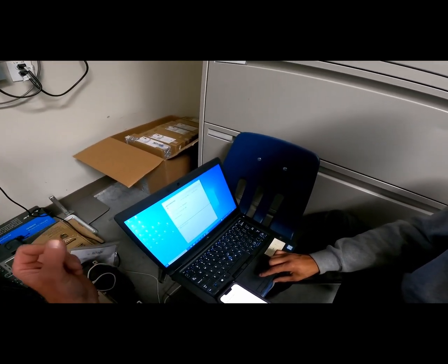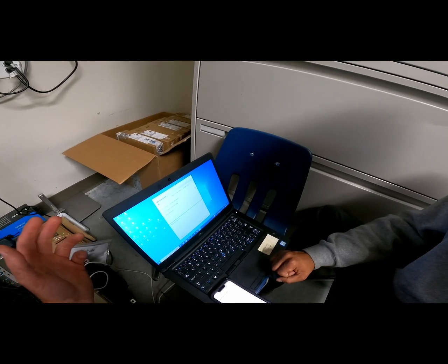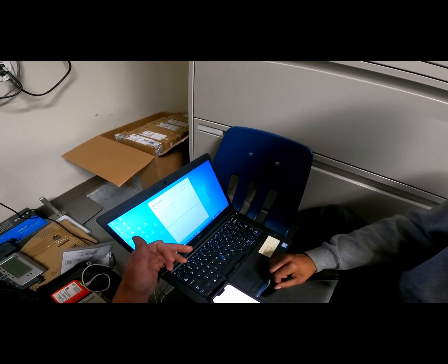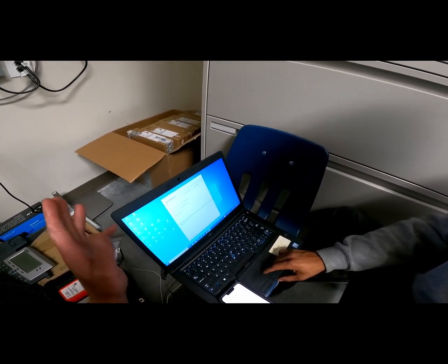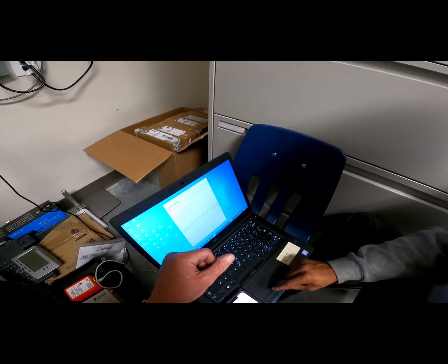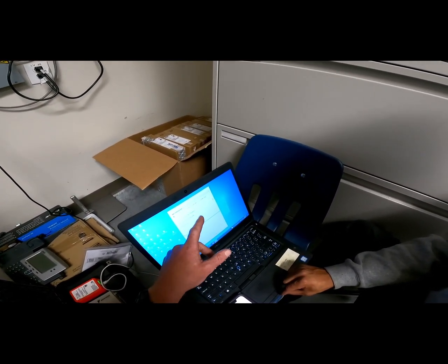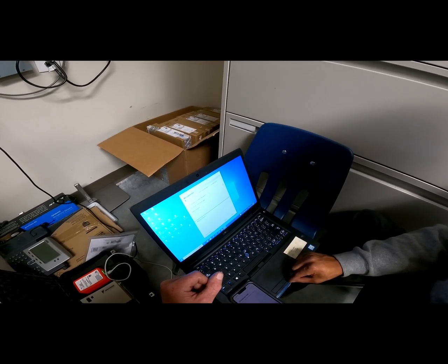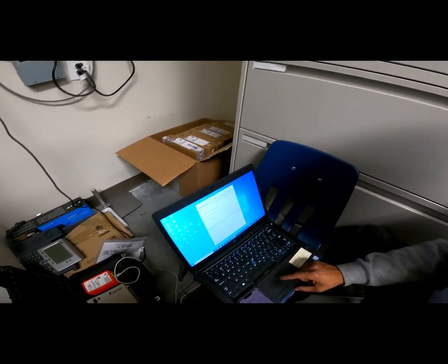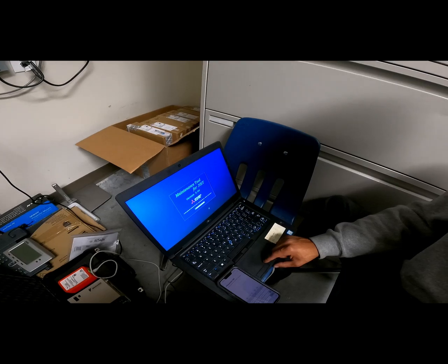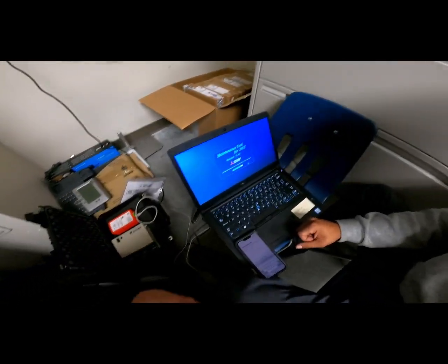If you had a file that you wanted to pull up to analyze, we'd go to offline analysis, right? But we're actually going to connect to the system itself, so we're going to use the MN converter. We know our COM port, and we know the version of maintenance tool we're using, you go ahead and click select. And it'll start pulling up.